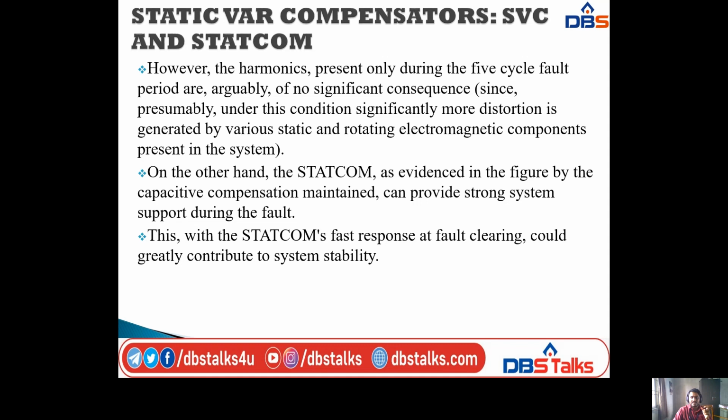On the other hand, the STATCOM, as evidenced in the figure by the capacitive compensation maintained, can provide strong system support during the fault. This, with the STATCOM's faster response at fault clearing, could greatly contribute to system stability.